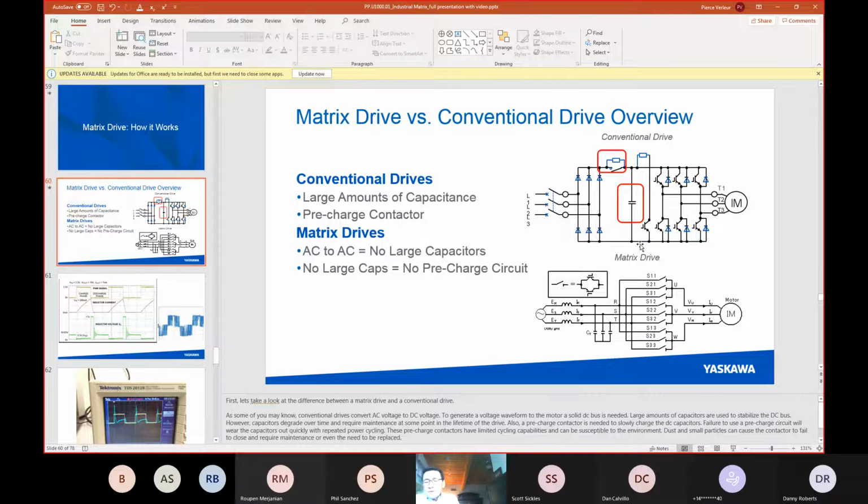So here's your incoming line. Here's that separation I was talking about, the diode bridge, and this is what the control board on the conventional PWM drive can see. Now let's go back to some real basics here. We are trying to control a motor. It is an AC induction motor, and in an AC induction motor, current is torque. What are we really trying to produce on the output of that motor? Torque. Therefore, we're trying to control current in the motor, and our only method of controlling that is voltage.